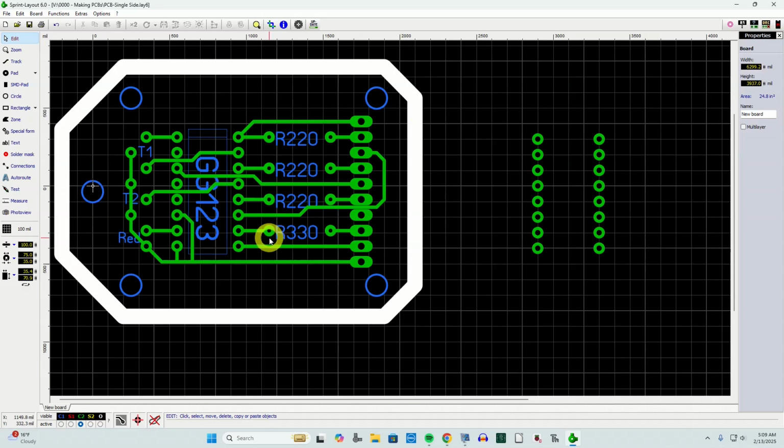Next up, I'm going to create our resistor pads going off to the right. And you'll notice that the hole is a little smaller. So when I select my pad, I'm going to make the hole smaller. I usually try to size the holes, that's really wrong. Oh no, we're good. I usually try to size those holes close to the lead size so that the lead of the component will fit in the hole easily and it slides right in, but not so loose that you end up with a gargantuan hole for a tiny wire. So we'll throw these pads in.